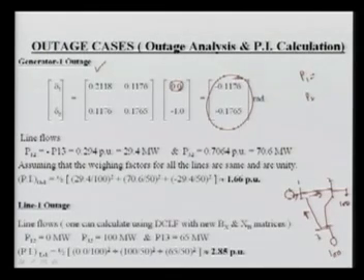The power which is flowing from 3 to 1 will be equal to 1 to 2. Or 1 to 3 will be the negative of 1 to 2, and that we have written. 1, 2 will be minus 1, 3, that is in this direction, because the power will be flowing here. And that we can calculate from this expression. It is 29.4 megawatt. Similarly, the remaining power of 100 will be going 70.6 here. So this is rerouted. And now we can form the PI.